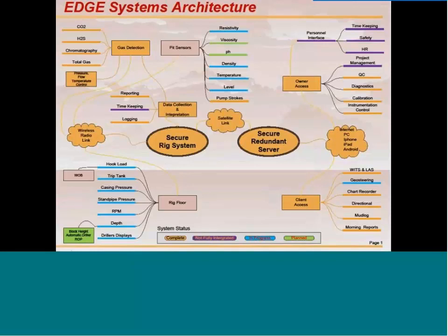The next diagram is a brief look at the type of sensors and systems that we acquire data from, and some of the sensors you could acquire data once a minute and it would be plenty fast enough. There are other sensors where we should be acquiring, and do acquire, the data at 1 kilohertz. We've been working on torque and drag software recently, and we're using 1 kilohertz to acquire data for it. Chromatography, we acquire data at about 25 hertz. So lots of different speeds of acquisition.